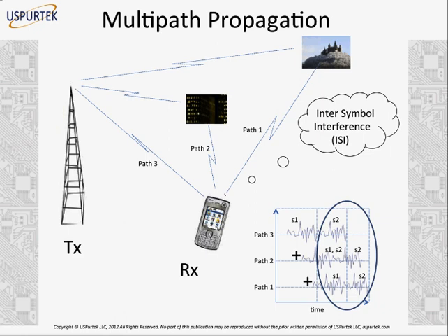Also a portion of symbol 2, which is a delayed copy, interferes with the one received on path 3. This can be a bigger problem. If we are receiving data over the air and all this is happening due to multipath propagation, the receiver will see the adjacent symbol superimposed and it will appear as useless or corrupted data bits, so we will miss data. So the challenge for mobile wireless system design is to remove or avoid the ISI, the inter-symbol interference.